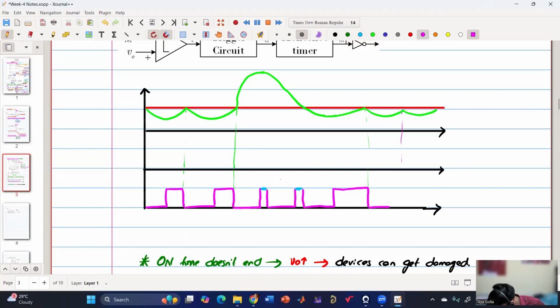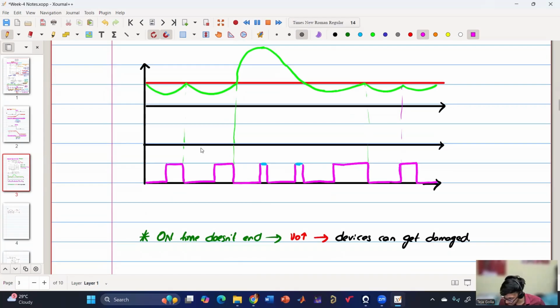So there it is slightly different. Here it is slightly different. If you see again here, the time period T1 is higher, and here T2 is small. So again, T2 is smaller than T1. So when the on time is minimum, the switching frequency will be maximum or the time period will be minimum. Is this part clear? Yes.